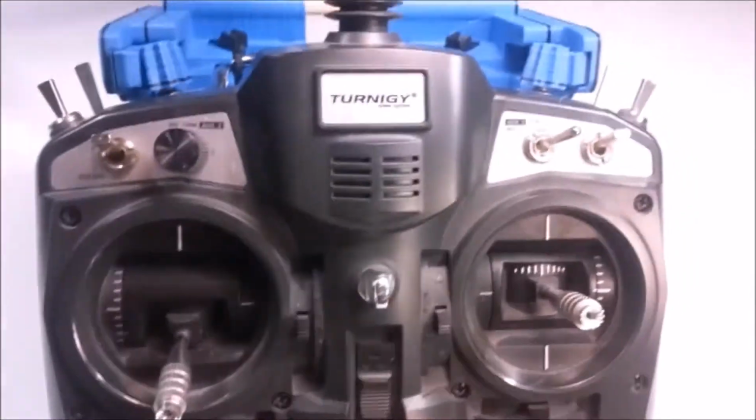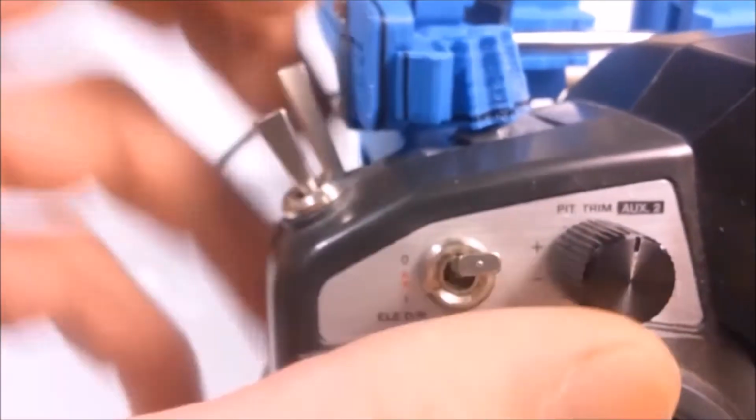Uploaded. So, alright, we're going to load the settings into the transmitter here. Now, if you have a switch in the wrong position on this controller, when you turn it on, you get a switch error. So, these ones up, these on the face up, these on the top back, away from you. Okay, so let's go into settings here. We're going to hold down the enter button. We'll just push up or down into the settings there.